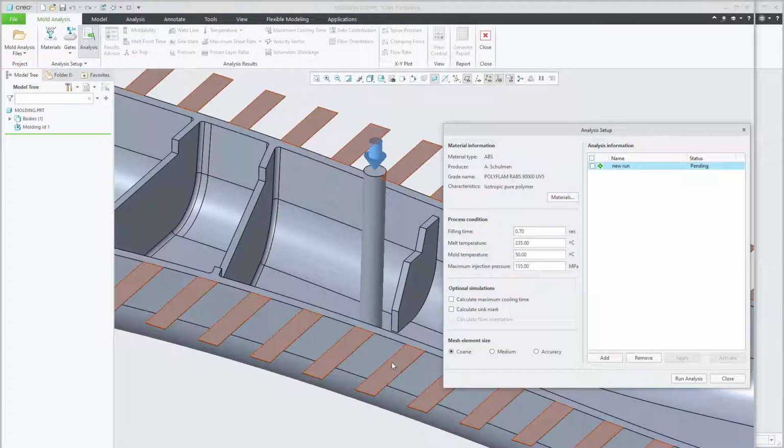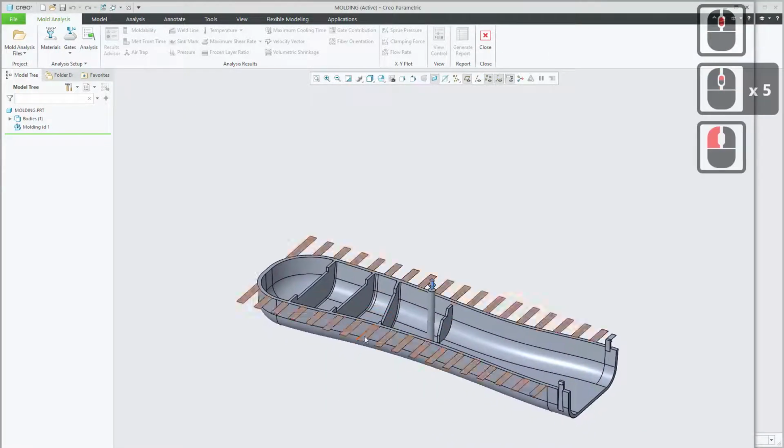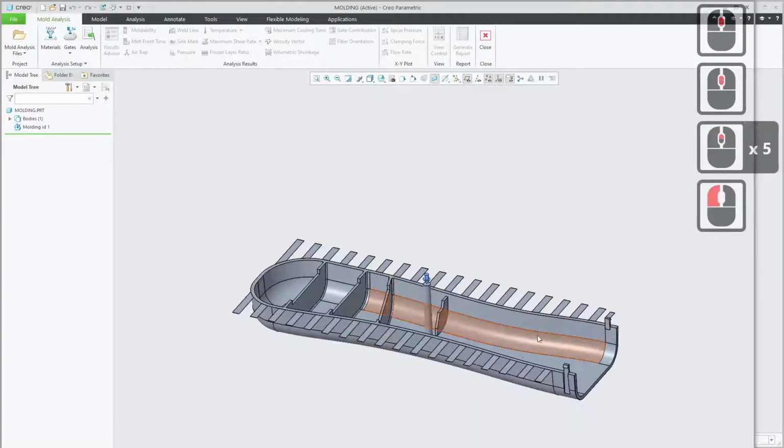persuaded to transition into these areas which are not intended to be on the finished part. These areas are consumable. If we have air traps in them, we don't care at all. So we've moved the air traps away from the moulding itself. And obviously there are areas on this mould design that could probably do with some more air traps added.